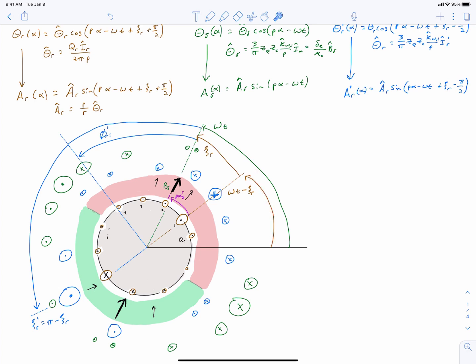And following the convention of the AC machine sizing unit from the other month, we can label a zeta r prime, which is the distance from the peak of our stator linear current density due to the rotor fields, coming out of the page, from the axis of our magnetizing field. And so that's this angle that we've plotted up here. And so you can compare this in your notes to what we had in the original AC machine design sizing equations.